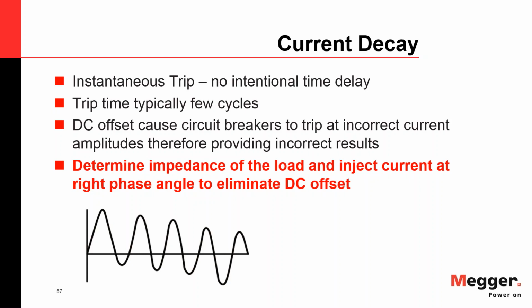It's a very time consuming process, but the standards call for it to be done. No asymmetrical component. So it would be very nice to have a tester that can actually measure all of that, and have a source that can be turned on in a way that the DC offset is fully compensated.